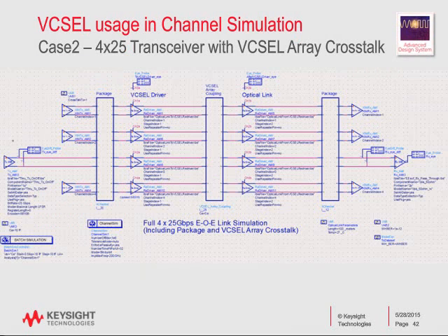Now, one of the other issues that can come up in discussion is, well, you have your optical link. Can I break into that link? Can I do anything in the link? One thing that you might want to model, for example, is the coupling inside of the VCSEL array. The VCSEL, in a sense like this, will probably be a number of VCSELs all on one piece of semiconductor. And guess what? When you're feeding them, there's an amount of crosstalk that's not modeled in the input and output channels of the package. It's actually right there at the die.